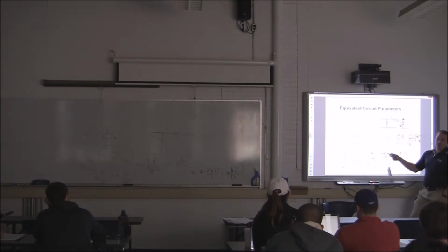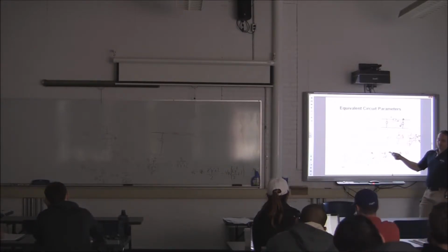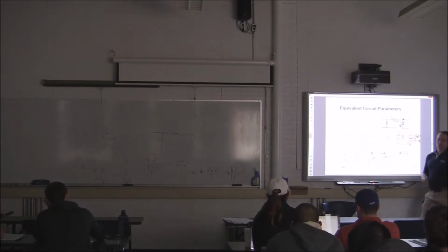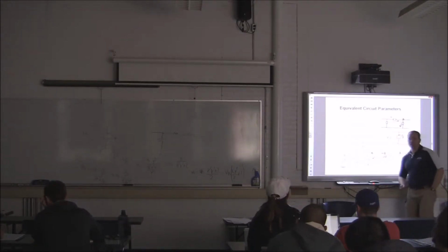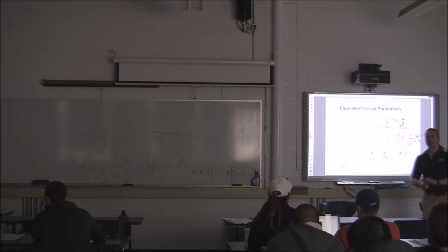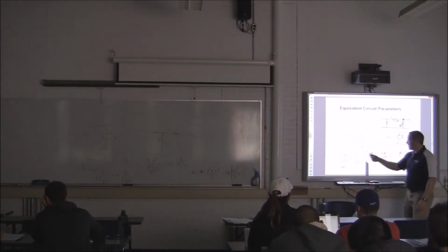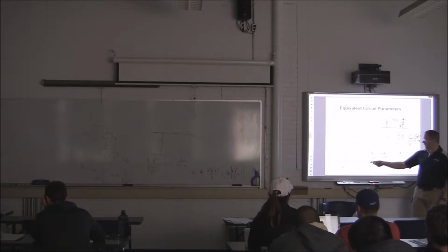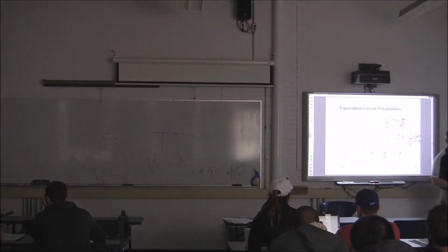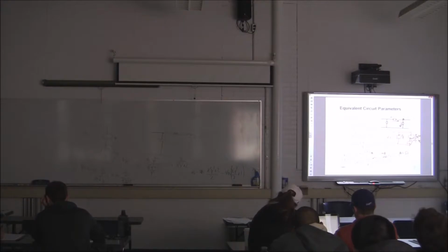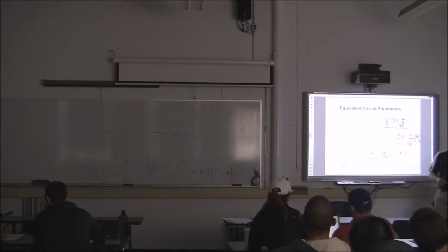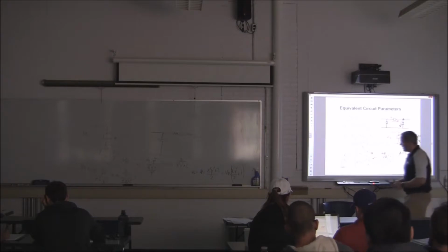What's the unit supposed to be with B? What times a current equals a volts? Ohms. That's an ohms. What about C? Supposed to be mhos, right? So this is essentially going to have the same units here, which is unitless. We end up with a Y prime in the front, which means it ends up with the units of mhos. And then we've already determined A, and since A and D are the same, we're good to go. So everything checks out. Our units are fine. Okay?